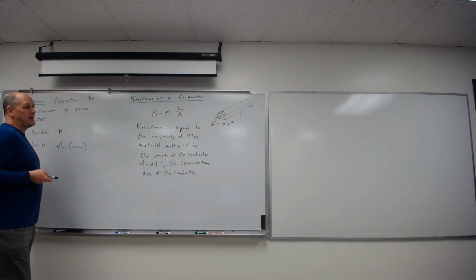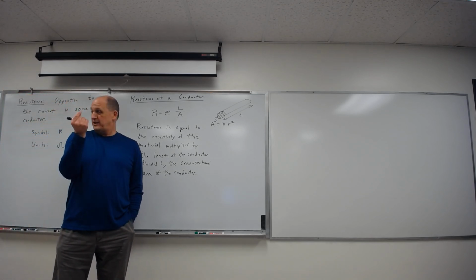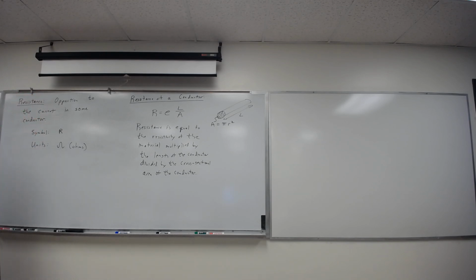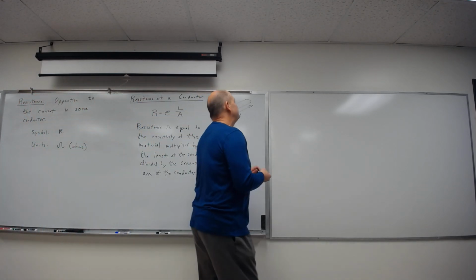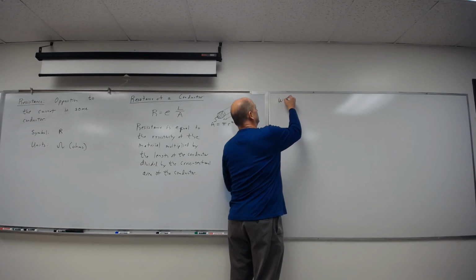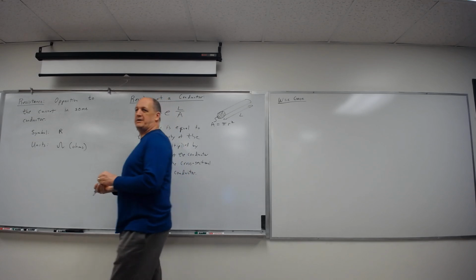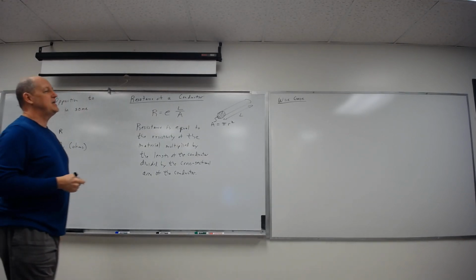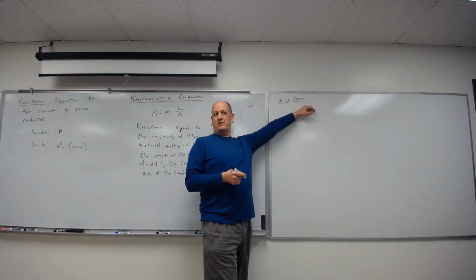Okay, we have a standard measurement we use in North America for wire and its area. It's really based on the diameter of it, but it transcribes to the area. Anybody know what that is? Gauge. Yeah, gauge. So wire gauges. I'm not going to even give you numbers right now because most of these numbers aren't probably going to mean a lot to you. We'll pull them up in a week or so in calculations. For now, I just want you to get an idea. First of all, wire gauges can be counterintuitive for people because big numbers are smaller and small numbers are bigger.